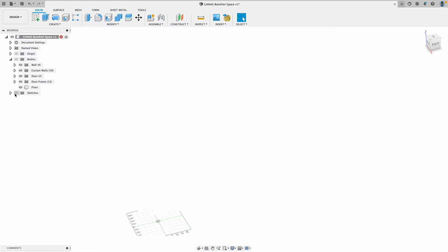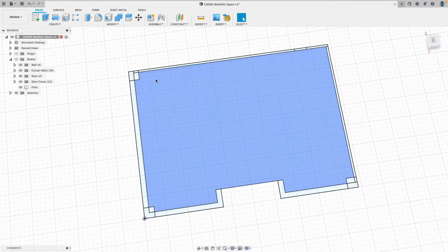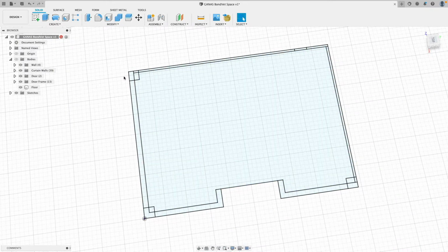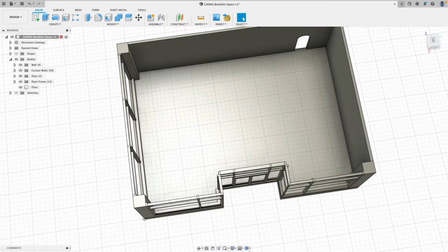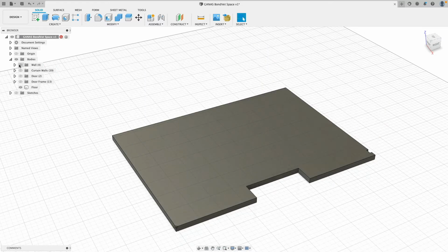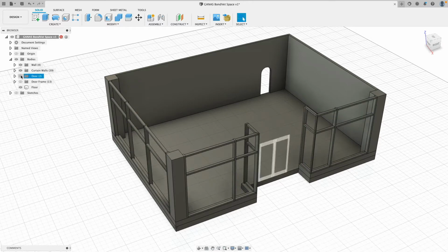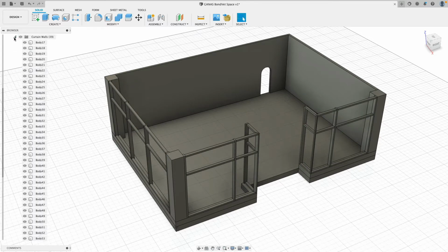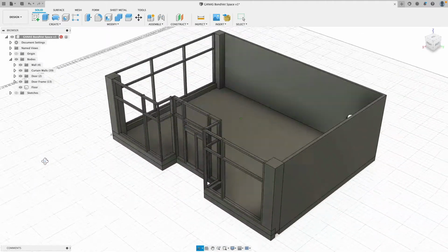This whole sketch, or this design, basically started only with one sketch, just for the rough layout, and then everything was modeled, as you can see, without the timeline, just in direct modeling. And I started by putting down the foundation, then the walls, and then actually the curtain walls with all the individual elements we have in there, the doors, and then everything that goes around the door.